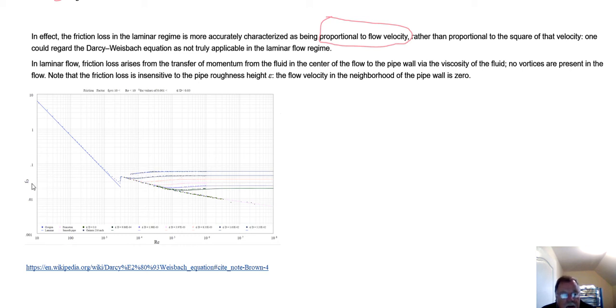But you arrive then at this point here where you get turbulent flow, and you can see that the variable function is now constant for different pipes. They're all different types of pipes, copper. So basically, once you go beyond that threshold and you have turbulent flow, which most systems will have, the square law is correct.